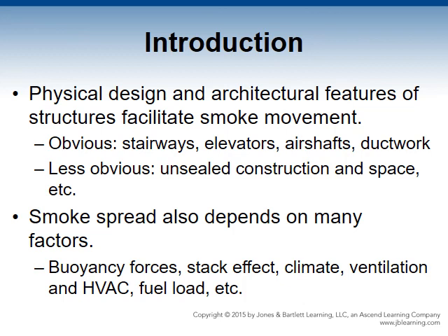Not so obvious pathways include unsealed construction openings at the interfaces of floors and perimeter walls, unsealed annular spaces around pipes, ducts, and conduits through the floor shaft, and incomplete shaft wall seals and smoke barrier walls at the junction of overhead floor structures. Smoke spread is influenced by other factors as well, such as buoyancy forces, stack effect, exterior wind and resulting forces,